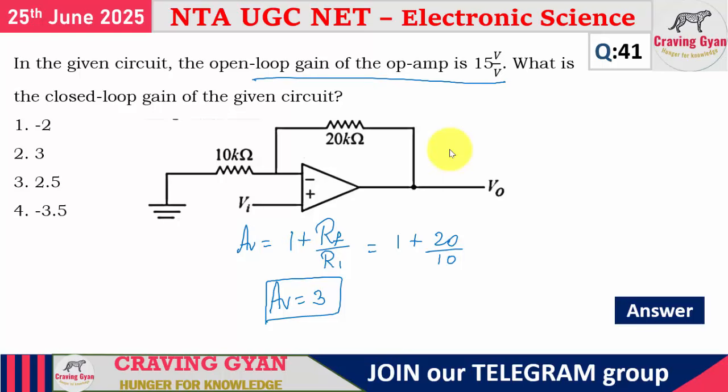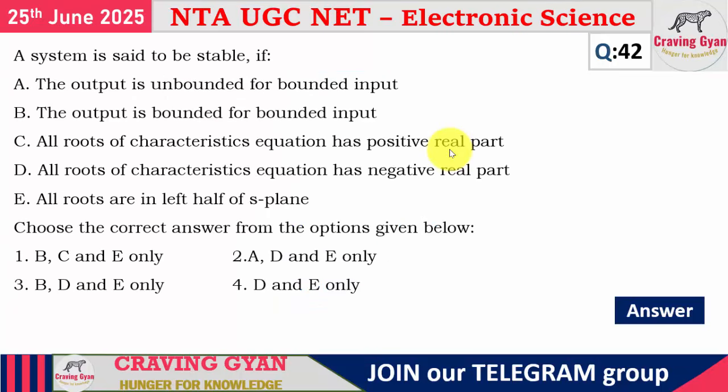Here, what is the open loop gain? Open loop gain is just 15, which is a very, very low value, right? It should be of the order of 10 power 5. So in this kind of question, is the formula applicable? Please comment your answers in the comment section, right?